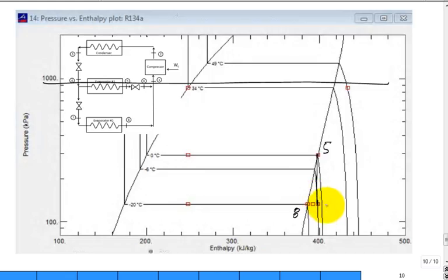So this is state 6, and then you just average the 6 depending on the mass fraction. It's 50-50 for this problem, and so that's state 1. And then the difficulty is we don't have a nice curve for an isentropic process, but that's a line of S equal to constant. It's sloped and bent a little bit, and that gets you up to state 2. And then this is state 3, and then this was state 4, and this was state 7, right? 7 down there.